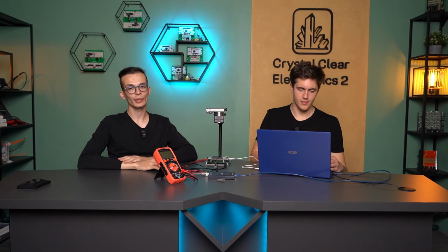The second task is to generate a sine wave. In this exercise, a sine wave of 100 points is calculated with the microcontroller, and the output analog signal is generated from this using two methods. In this exercise, we want the frequency of the sine signal to be 10 Hz.